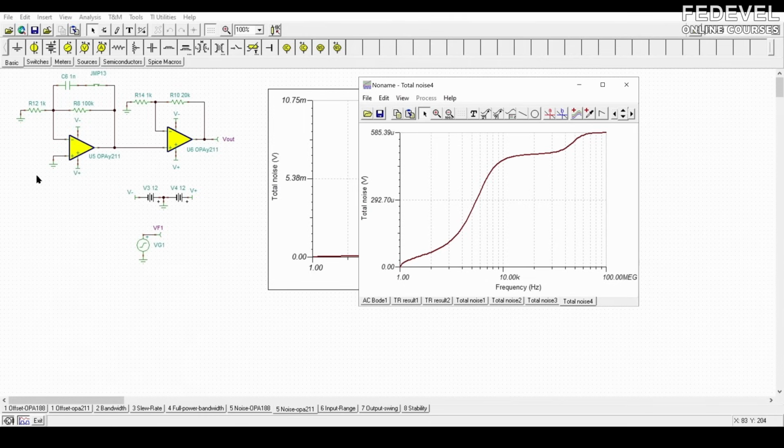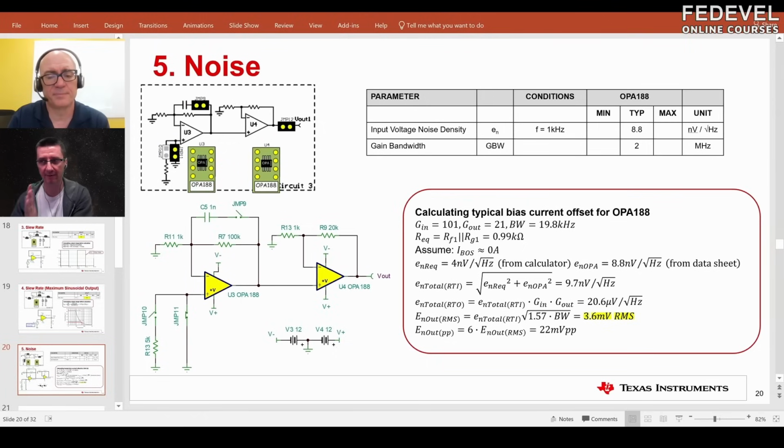So if you need, let's say, 20 hertz to 20 kilohertz, then you could limit your bandwidth. You wouldn't want to limit it to exactly 20 kilohertz; maybe you'd limit it to 200 kilohertz to give yourself a little margin, but you wouldn't need megahertz of bandwidth, and that would just be extra noise that you would get by leaving the circuit unfiltered. So the moral of the story is, to reduce noise, you filter to the greatest extent possible that your input signal will allow, because noise is generated for every single frequency, as we see in the graph.